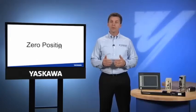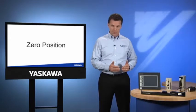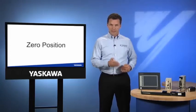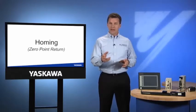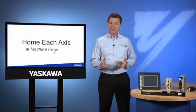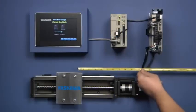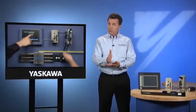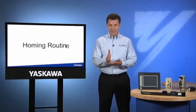Absolute positions and moves only make sense when compared to the absolute position which the controller has identified as 0. The machine requires a repeatable method to find this 0 point. This method is often called homing, or 0-point return. To reorient an axis that may have been moved while the power is off, the controller needs to home each axis every time the machine powers up. A very simple way to accomplish homing is for the operator to visually align the axis to its 0 position. In actual practice, however, most machines rely on a fully automated sequence called a homing routine.